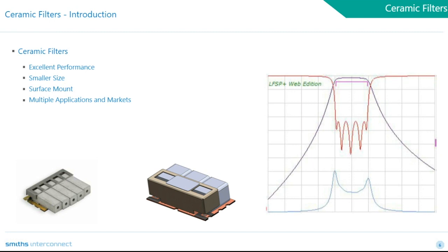The filters are comprised of high Q, high dielectric constant ceramic resonators, which are capacitively coupled and are typically connected to a surface mountable printed wiring board. The ceramic resonators are silver plated and also boast low temperature drift. The high relative dielectric constant allows for smaller size filter options, while the high Q available supports the low loss and high rejection these filters offer. My colleague Ron will get into more details on the filter theory a little later in the webinar.